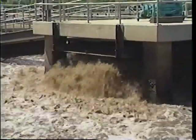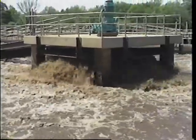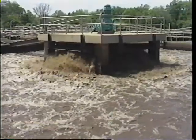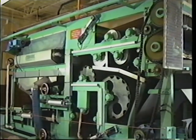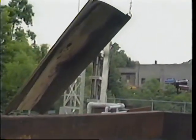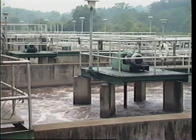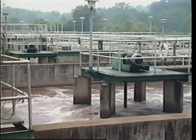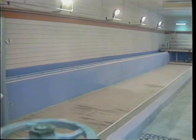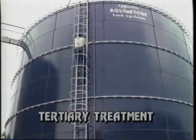The wastewater is next exposed to a secondary treatment process. In this process, carefully controlled bacteria within the secondary treatment process consume organic pollutants from the wastewater. Waste material and solids removed during the primary and secondary treatment processes go to solids handling facilities and onto disposal. At this stage, the wastewater may pass on to another biological treatment unit for nutrient removal or a sand filter for fine solids removal. This additional treatment stage is usually referred to as tertiary treatment.